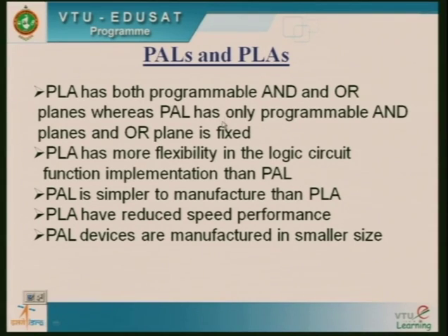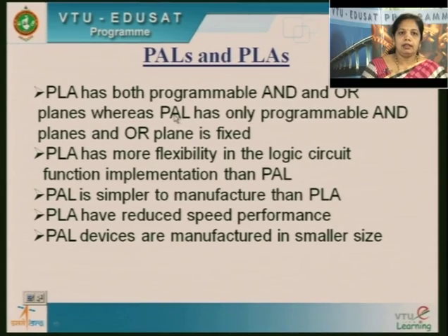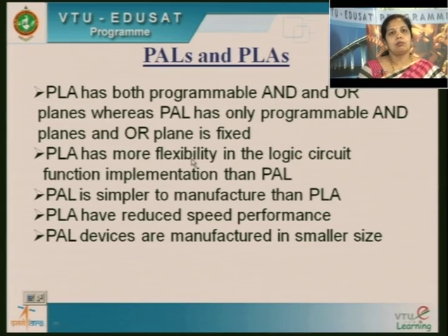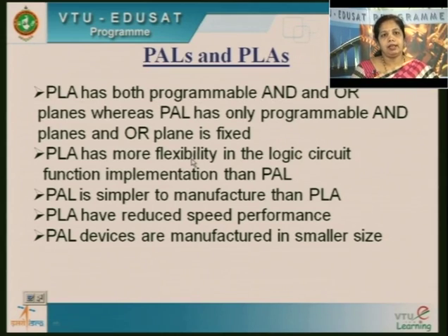In PAL, I can only program the AND plane, but the OR plane is fixed. So PLA has more flexibility in the logic circuit function implementation than PAL, since both the AND plane and OR plane are programmable.